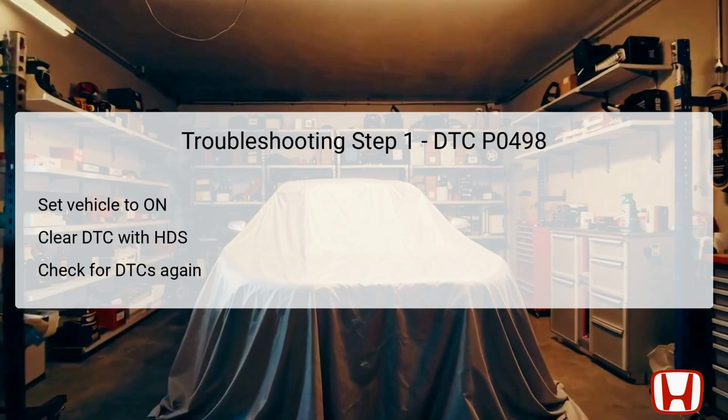After clearing the codes, perform another check for any pending or confirmed DTCs using the HDS. This step will help to ascertain whether DTC P0498 persists, indicating an ongoing issue that needs to be diagnosed. In this step, you will select the EVAP test option from the inspection menu of the HDS. This diagnostic option allows you to test the ventilation function of the EVAP system.